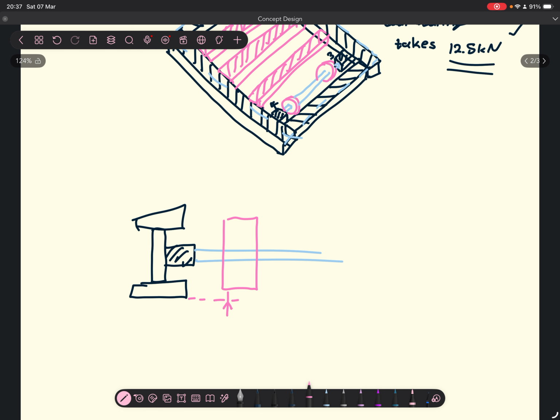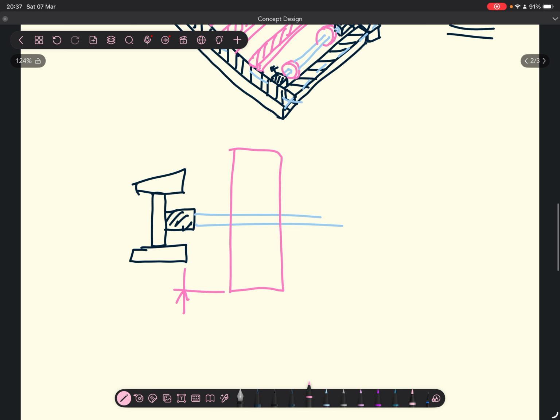Reasons why you wouldn't want that is if there's a rock or something in front of your funicular, then the frame is going to hit that rock, right? So in most cases you would probably want the frame to be above the wheel, so you'd want something like that where the gap is in the opposite direction, so there's some clearance between the ground and your frame.